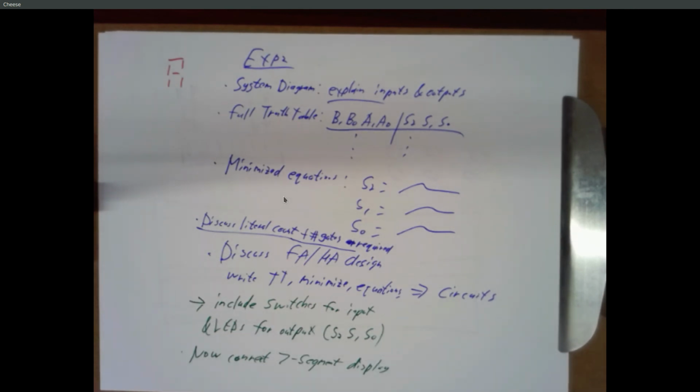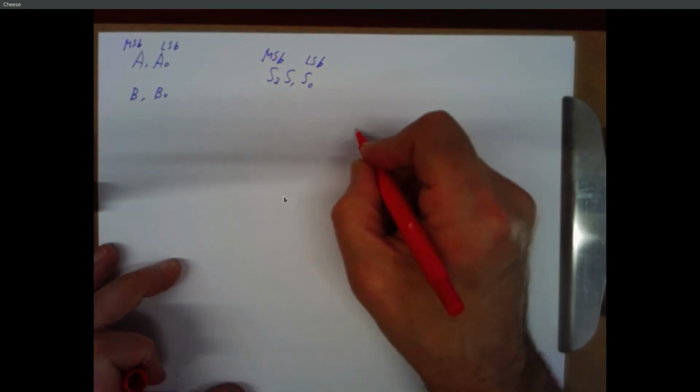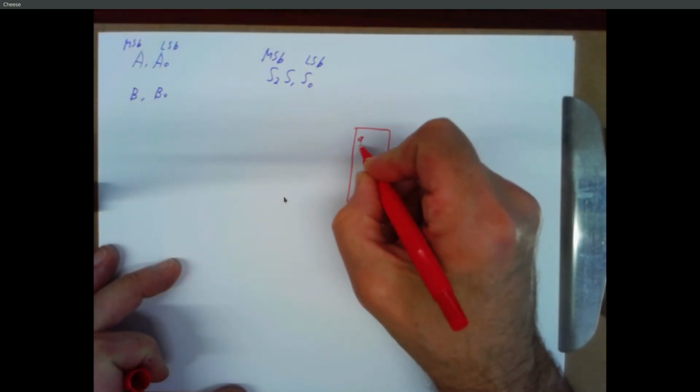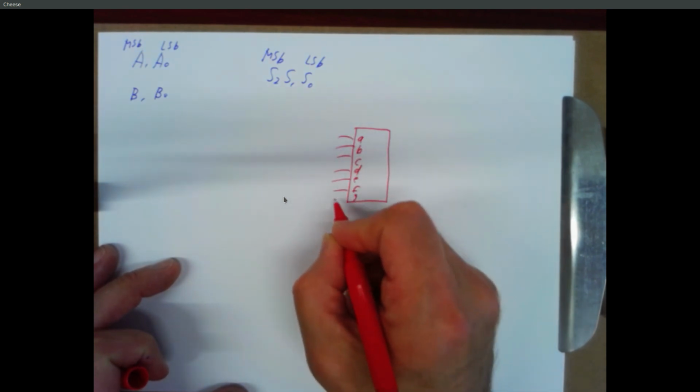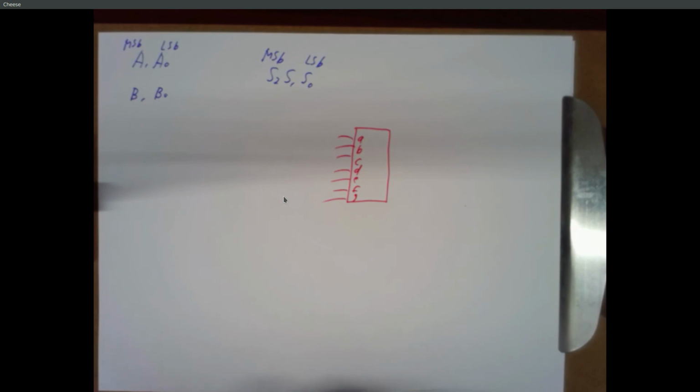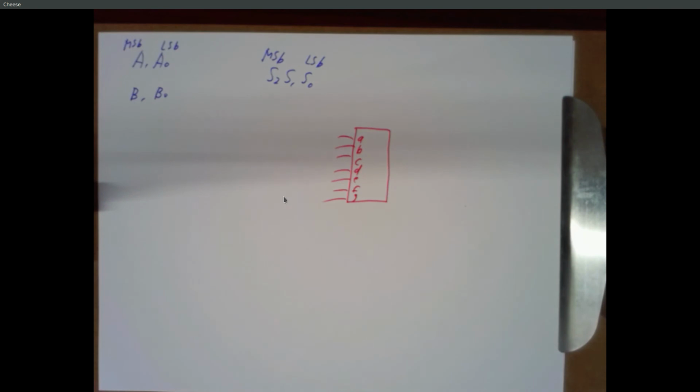How do we actually draw the 74LS32 and the LED in our circuit diagram? The 7-segment display, you mean? Yeah, that. So 7-segment display, you could do it just like this. And just show your inputs to it like that. And just label it in your component ID block as 7-segment display. And that's easier than trying to like draw the wires over to the segments, but anything that makes it clear there will be good.